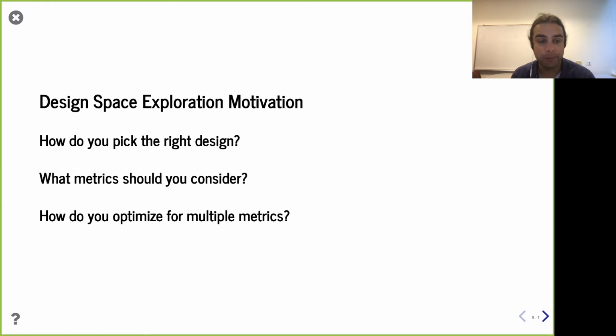The way people often refer to this is what's called design space exploration. We're basically going to say, of all the possible things we could do, which one should we actually do? Of course, it's easy to say, oh, I will make every possible hardware design, evaluate every possible hardware design, and pick the best one, but you probably should have some doubts about it because that's clearly not possible. It's going to be intractable. So instead, how do you identify and scope out the extent of the design space? What are the possibilities? And then within those possibilities, how do you go about picking the right design?